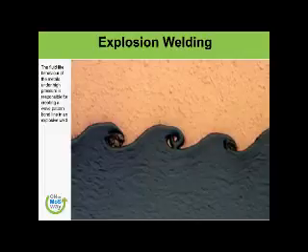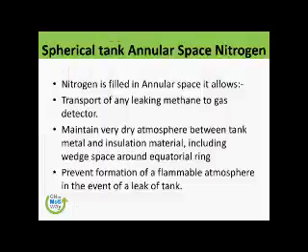Now, in a spherical tank, on the first day I explained to you about the annular spaces. Nitrogen is filled in annular spaces. It allows transport of any leakage of methane to gas detectors. Because that annular space is continuously being recycled with nitrogen, anything coming out of it is sniffed by the gas detectors, and if the gas detector detects, then they can easily tell us that yes, there is a leakage in the system or in the tank.